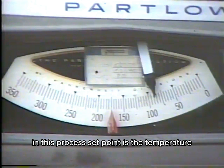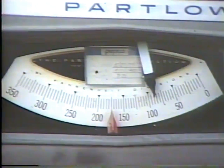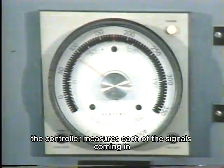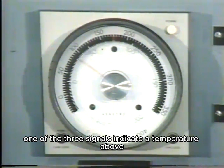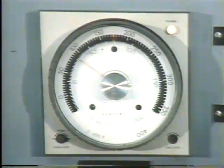In this process, set point is the temperature at which the control system takes action to prevent damage to the rubber lining. The temperature measurements at each of the transmitters are converted to signals that are sent to a controller. The controller measures each of the signals coming in and compares them to set point. If any one of the 3 signals indicate a temperature above 175 degrees, the controller produces a corrective output signal.